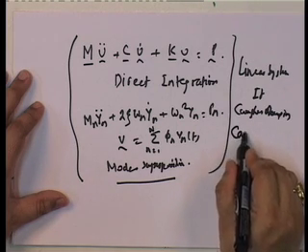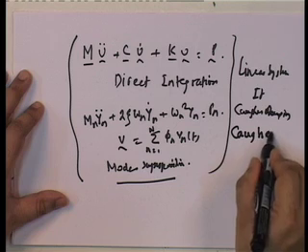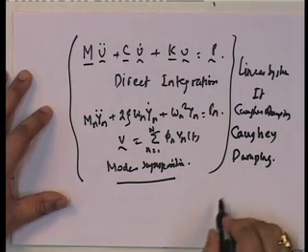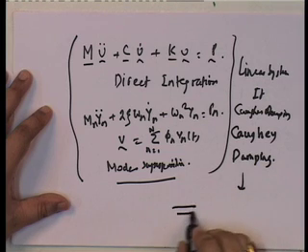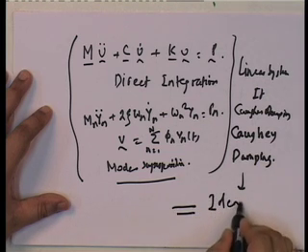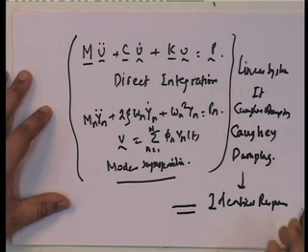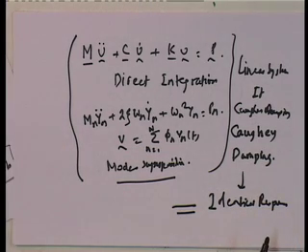Let me just write it down again. Caughey damping gives identical response. Okay? If you use mass proportional, if you use stiffness proportional, or if you use Rayleigh damping, you are not going to get the same between the two.